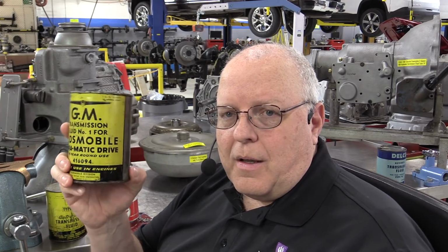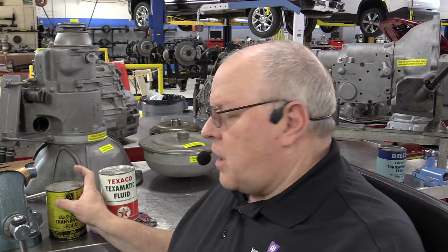Well, that wasn't happening. So instead, motor oil was being poured into the 1940 through 48 Hydra-Matic transmissions rather than the official fluid that it called for. And this was, of course, causing problems, especially cold weather related failures. The oil would be too thick, would cause delayed engagements and burned clutches and other issues that are common to cold weather automatic transmissions. So for 1949, General Motors developed an industry-wide Type A fluid specification.